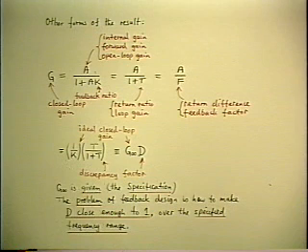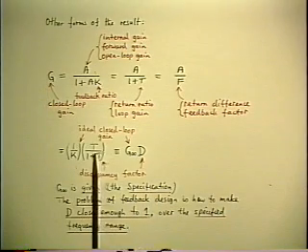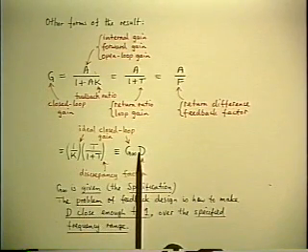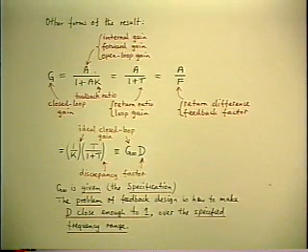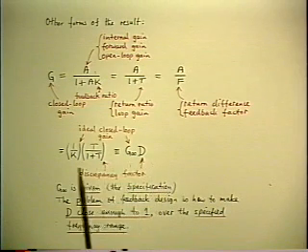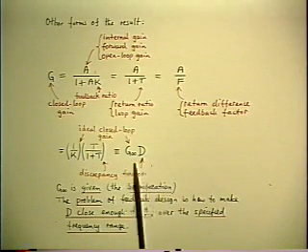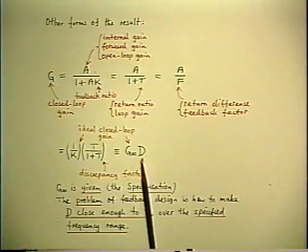And those are basically the only quantities that you really care about in the feedback system. Because if the answer is expressed entirely in terms of those two quantities, then that's all you need to know. And the A has, if not vanished, at least it's been relegated to a position of much less significance.